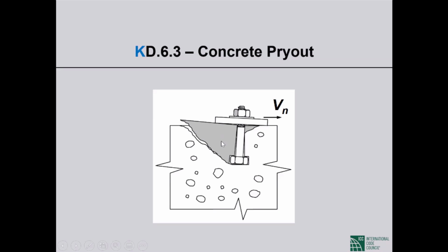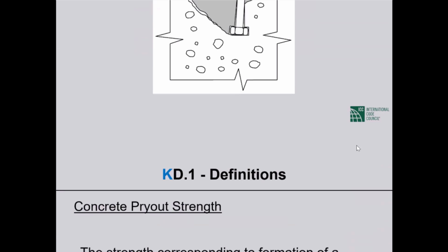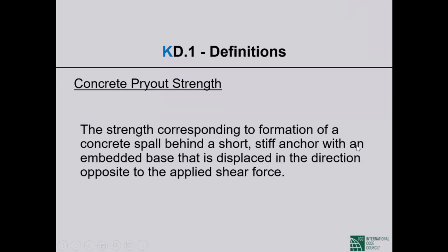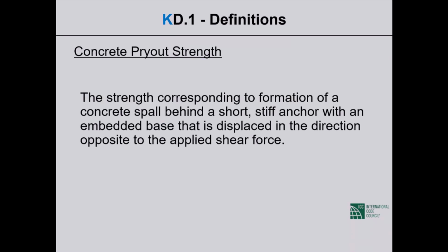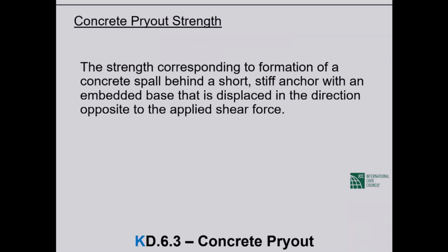Okay. So anchor reinforcement in shear, very, very important in applications, and that's as much as I'm able to show you. Pry out failure, I think this picture is very, very graphic. So this is a shallow anchor. Under shear, it kicks out and destroys the thin cover concrete to the top. The language describes the picture, so it is unnecessary to go into.